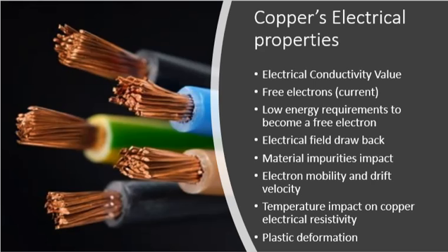The last big player in increasing resistivity is plastic deformation. Stretching copper past the linear region will cause more impurities and vacancies within the material, thus causing increased opposing electric field forces when current is transferred through it.